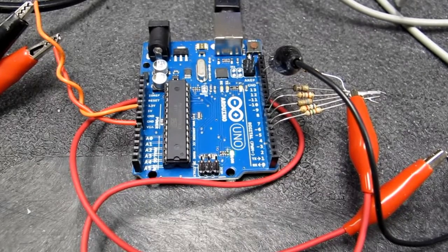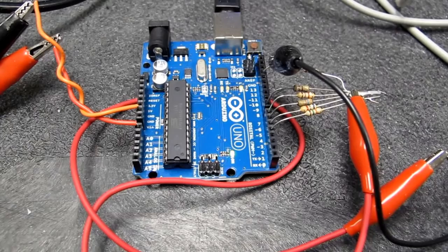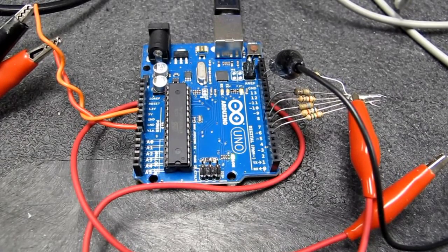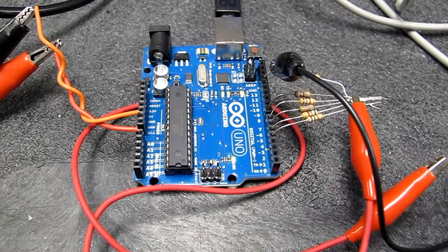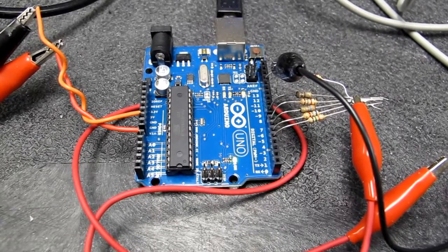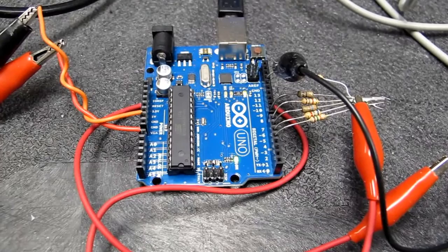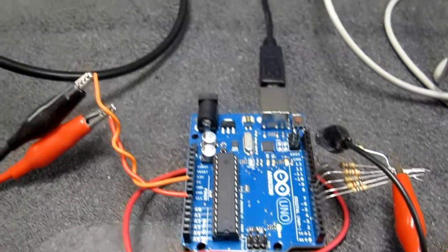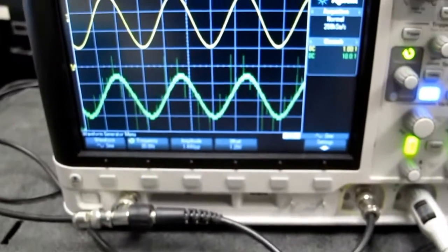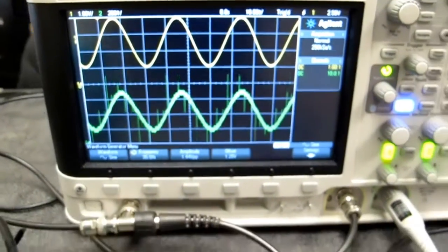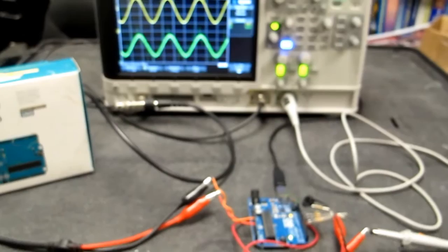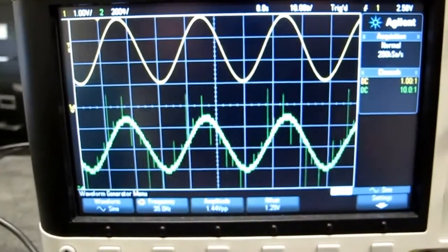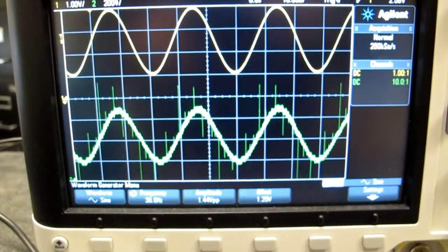We're looking at an Arduino board on which is a program that has one A to D input and a D to A output created with those 6 resistors you see on the right, creating a 5-bit word. And the results of the DSP program are shown on the scope screen here. Here's the big setup. Picture of the setup. The scope screen shows the input signal on the top and the output signal on the bottom.